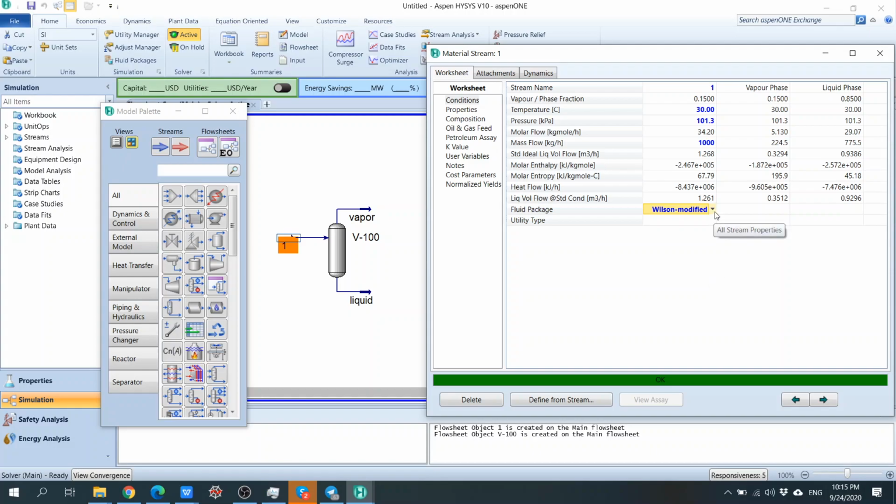So we could see that if we use the binary interaction parameters estimated by the UNIFAC, it's 15%, and this also 15%. So it shows how strongly these binary interaction parameters affect how much of a component goes in the vapor and in the liquid. While the original models, they differ quite a lot.